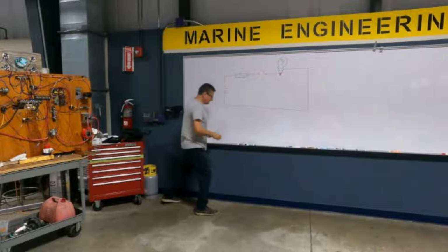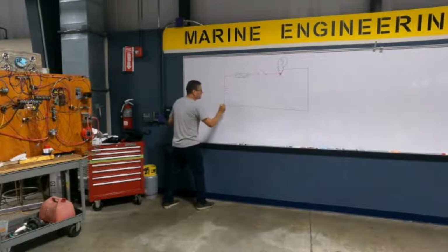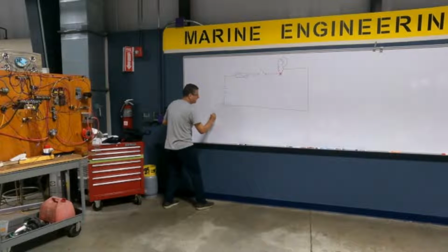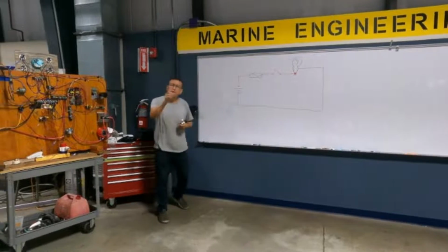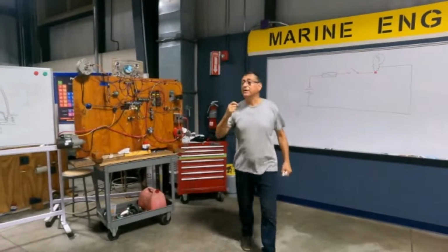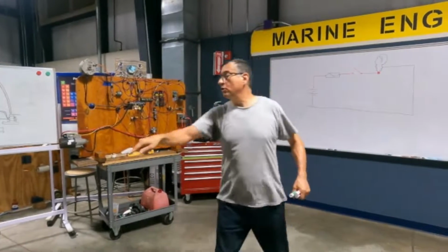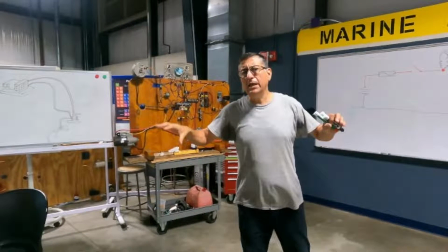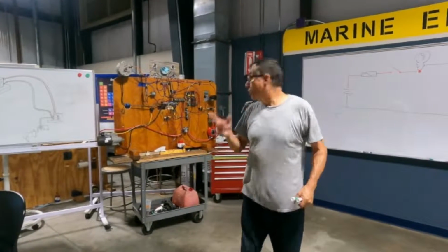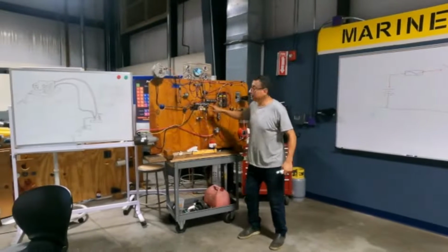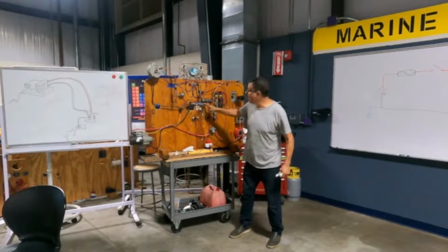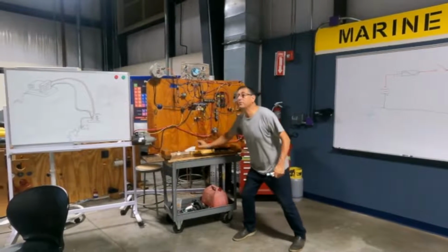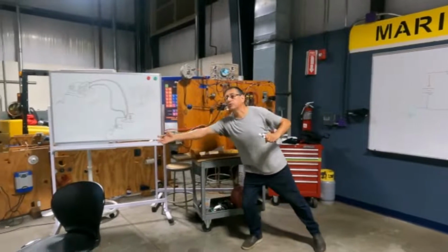And this point of return, guys, is connected to the ground. The negative is always connected to the ground. This is why you say in DC, oh, your ground. But really, of course, the ground bus bar, the negative bus bar, at the end of the day will be connected with a green cable, the bonding conductor, and connected to the sink.